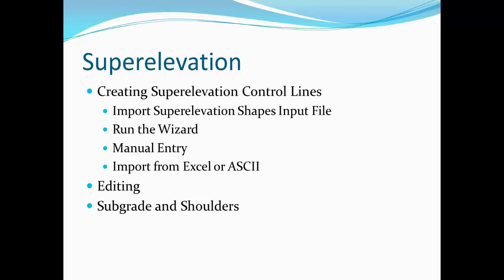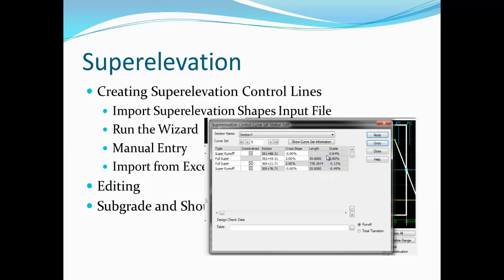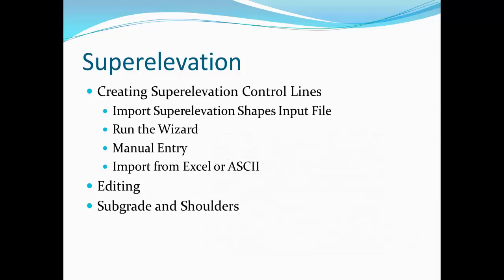Once you have some superelevation control lines, they can be edited in a number of different ways, either as a curve set, as the entire curve and transitions in one dialog, or as individual points in a superelevation diagram. Either way will work and depends on user preference.